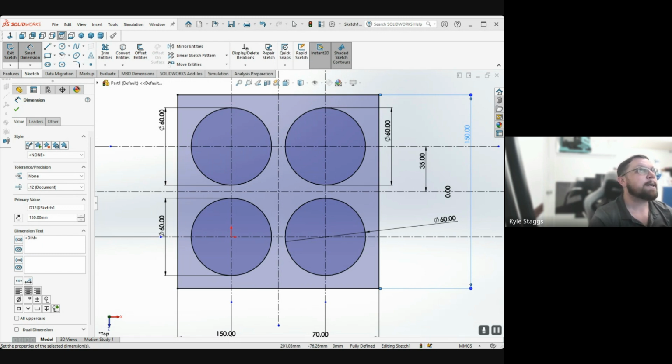You want to be able to use things like the scroll wheel. One of the settings that you're going to want to also pay attention to is up here at the gear under system options. What you're going to do is search for mouse, and it'll say mouse speed, or this one, the reverse mouse wheel and zoom direction.